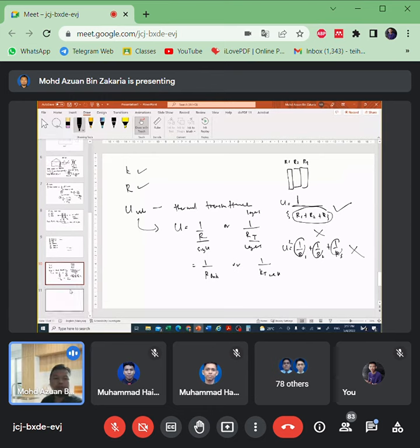So what you already covered is okay, we have a building. Remember the purpose of this is we want to know heat transfer to the building, right? How much heat can be transferred? So we want to calculate the building properties. To calculate the building properties, we need to know K value, R value, and U value, because in the end, we want to know how much heat can be transferred to the surface of the wall.